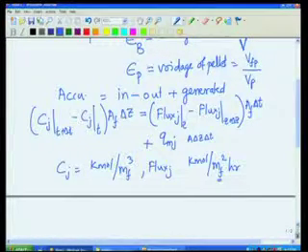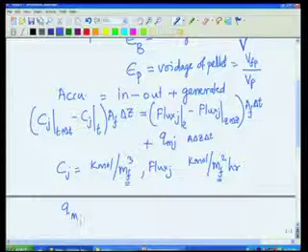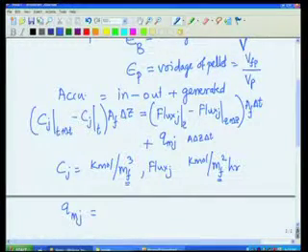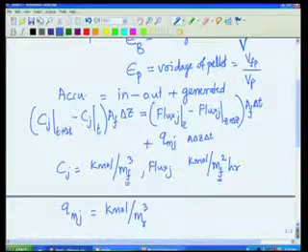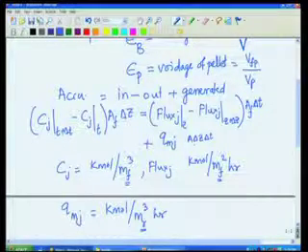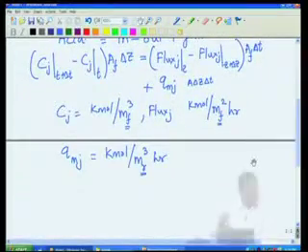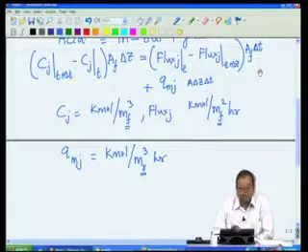Again the fluid volume, both these are per fluid volume, and the reason why we choose this will become clear. Qmj, we are going to call it kilomole per reactor volume per hour, and therefore this is per reactor volume, and we multiplied it by reactor volume A delta Z in our mass balance equation. Okay. So, this is my mass balance equation.